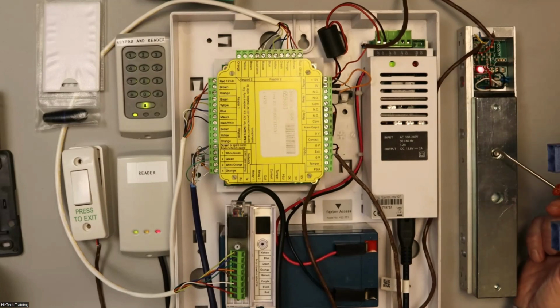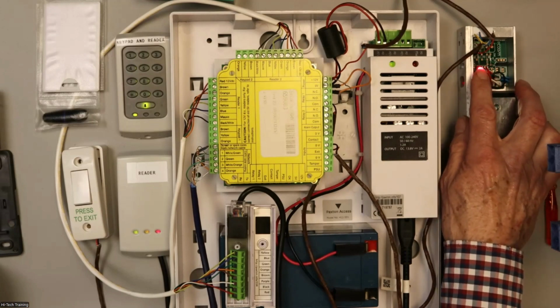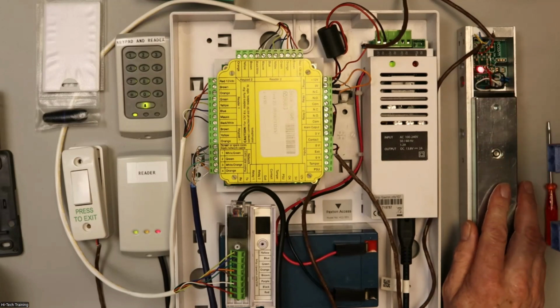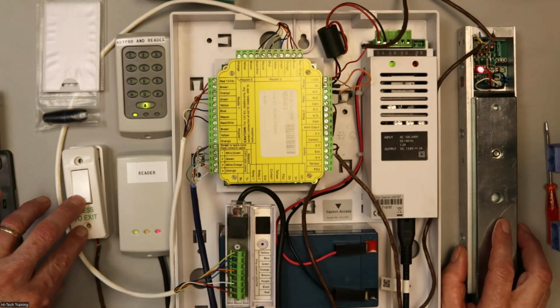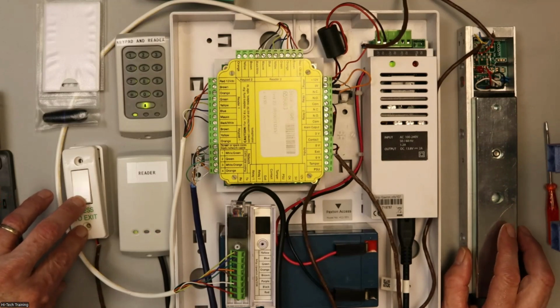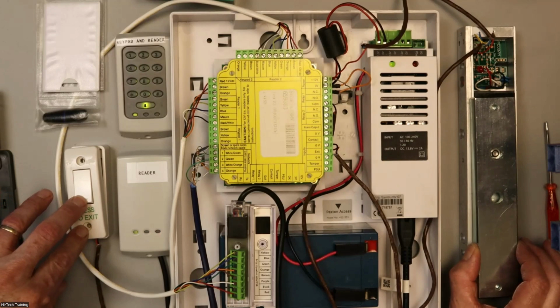On the right-hand side, we've got a Maglock, so that's powered on all the time. I just put a little LED here to show you that it's powered on. I can open it here with the exit button, so you'll see the magnet here will jump up. Yes, it comes up a little bit there. I've set this for, I think, 8 seconds. It stays off for 8 seconds, and it should lock again then.